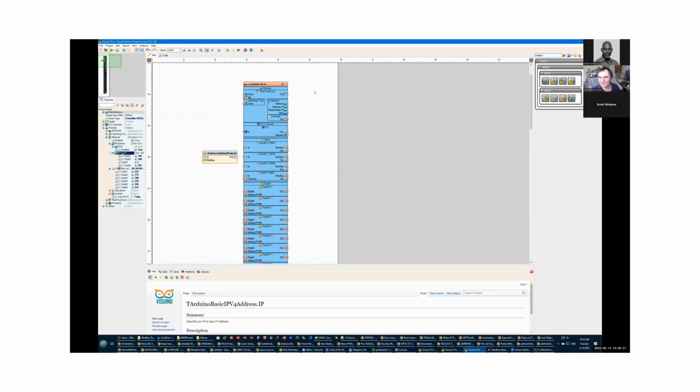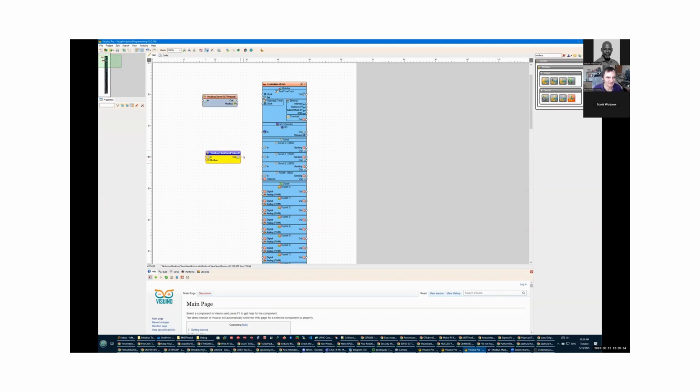And then we'll connect that to the Modbus server. So the server will be TCP, the client will be serial. They'll connect to each other. So the two protocols will basically talk to each other. So one protocol will send data to the other.